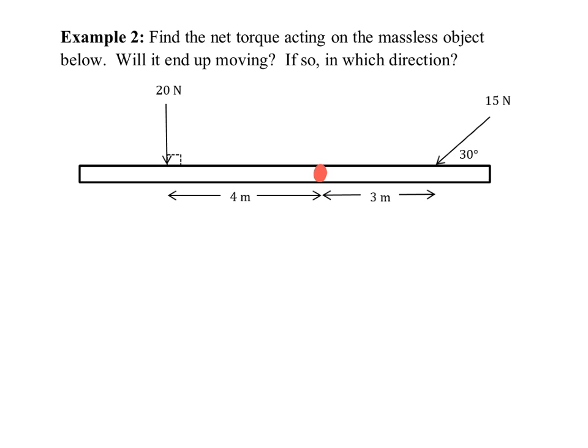So it's important that we recognize a way to dictate negative and positive torque. Again, if you recall, clockwise we said I despise, and counterclockwise we like. So those are the types of torque we get from the direction it would cause. So this force over here, because it causes clockwise rotation, will generate a negative torque. This force over here, because it causes counterclockwise rotation, that will generate a positive torque. So it's important that we recognize that the forces applied generate either positive or negative torques.